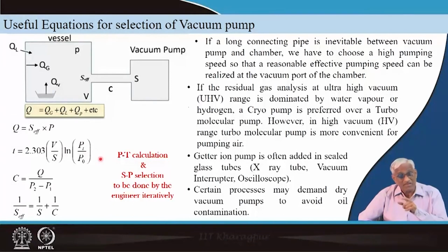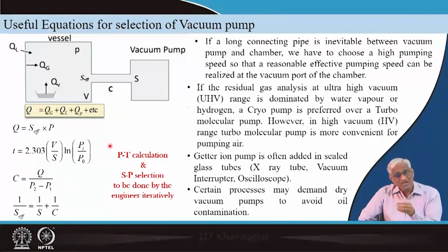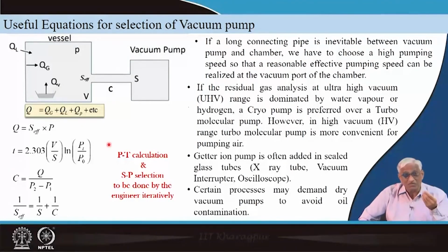Okay? Because initial evacuation to 0.1 torr and treating and ion etching, cleaning, holding and with a magnetic arm opening the gate valve, all these operations should be done fast. That is the weakest link. If you take longer time, you are gone. Does not matter even if you use little dirty pumps, you apply huge pumping speeds.